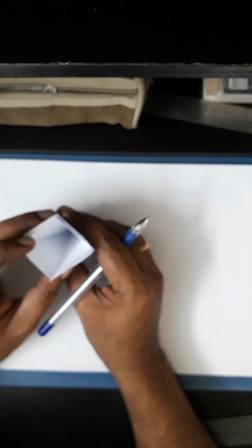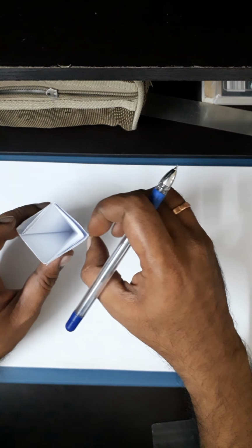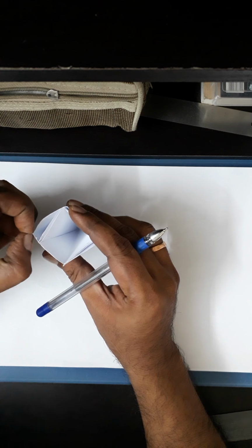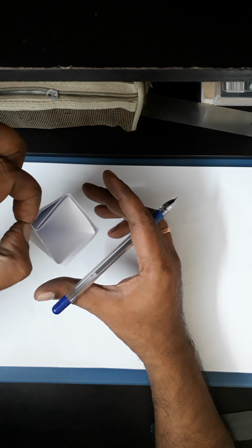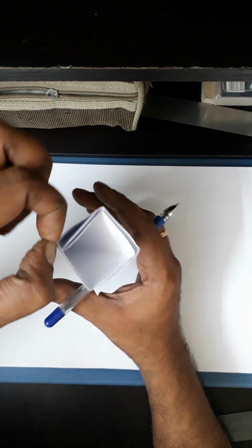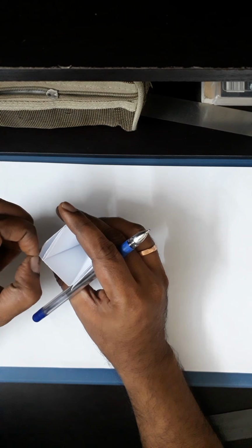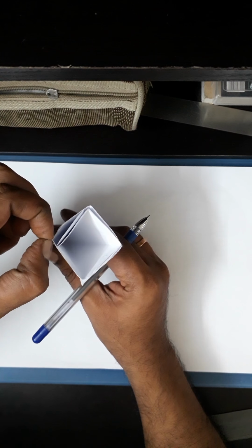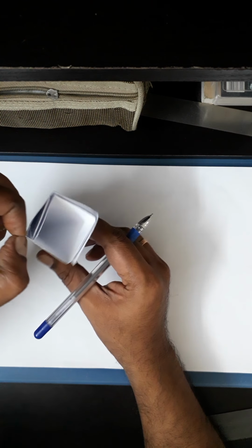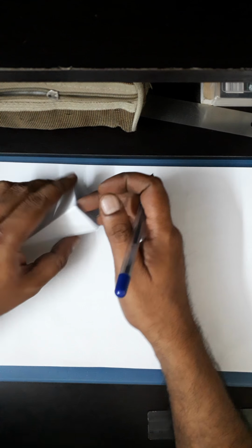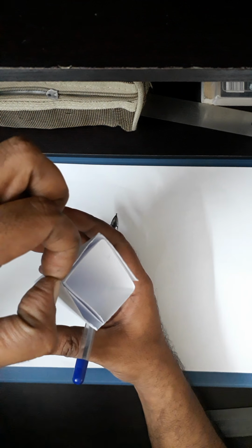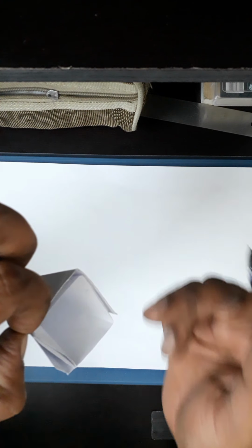In that case, it is better to keep the solid resting on its apex on HP, so that when I suspend about the base corner, the solid should automatically turn like this. Then the turning of the pyramid will be very limited. It will turn from this position to this when I freely suspend about this corner.